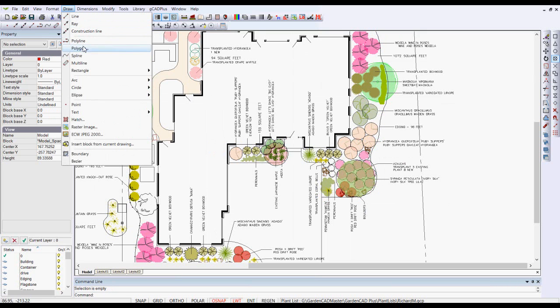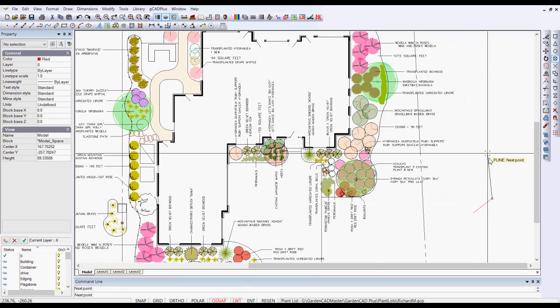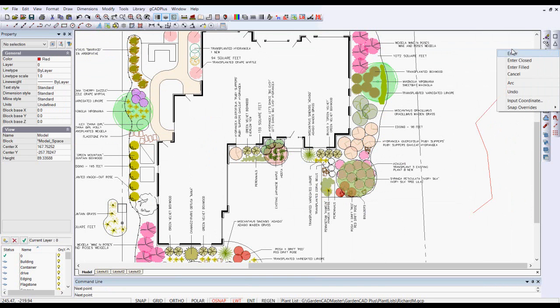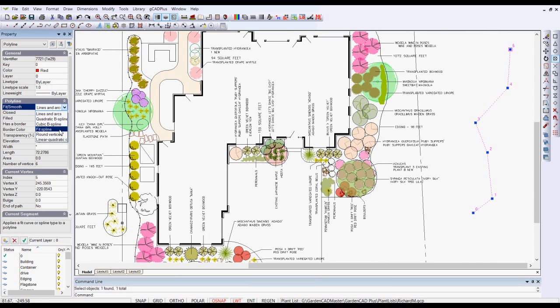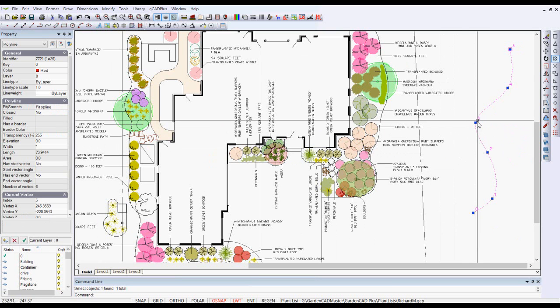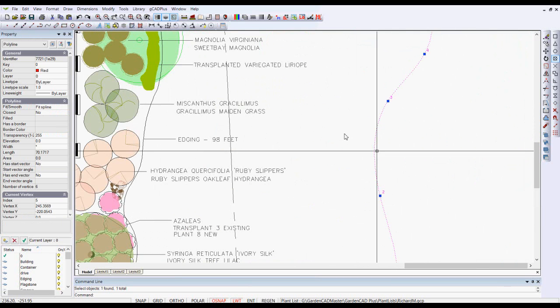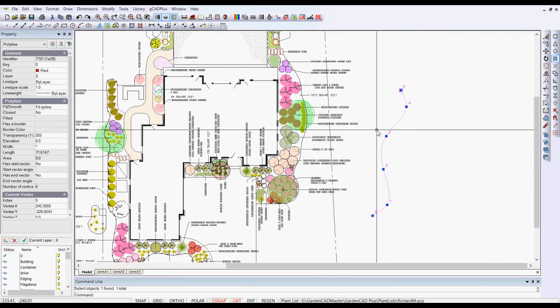Remember that if you put a polyline down, and we'll come over here and do it, just separate your curve in that way, enter it, pick it, and apply some spline curve to it. Once you've done that, it's a very easy matter then to bend and move the polyline and control the shape.